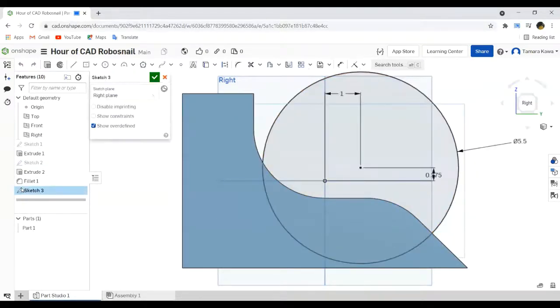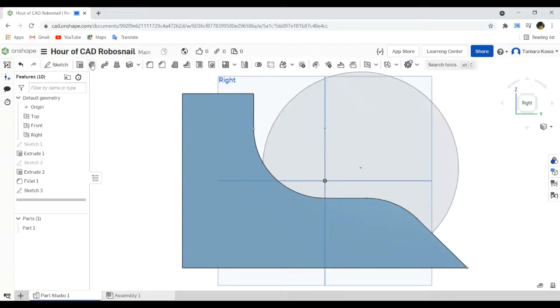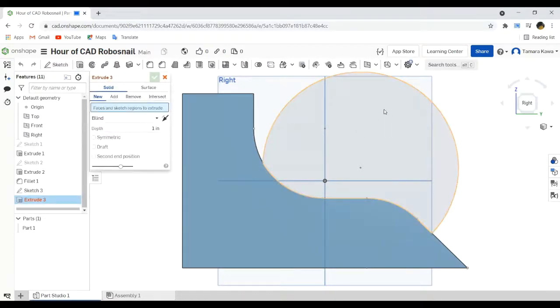I'm going to go back into the sketch. Again, I don't expect you to follow along this part, just watch. And watch this. I'm going to click on use. And I'm going to click on these lines. And you'll notice that they're starting to turn dark black because these lines are now being carried into the sketch. And you can also, by that same token, get rid of lines. So clicking on these scissors will get rid of all the spare lines. And now when we leave the sketch and try to extrude, it will show us just this section.